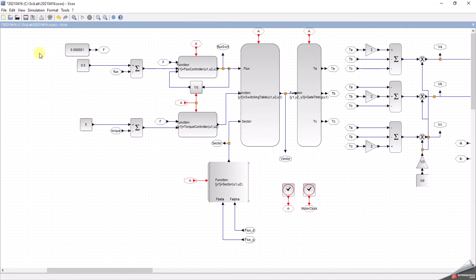So that would be external to the converter, and you would have some interface to that, whether 4 to 20 milliamps or 0 to 10 volts, 0 to 5 or whatever you choose. So that would be a PLC or some type of PEC, programmable electronic controller of some sort.